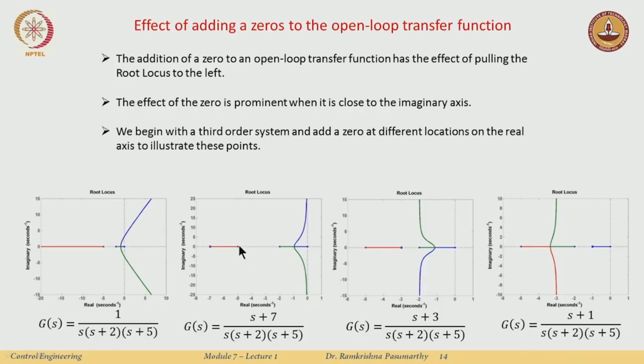So, this guy again will just move to the right and stop here, and now I see that the root locus has improved much, because if I were to deal with this gain here, you see that I am close to the verge of instability, right, this and this. So, this kind of adding a 0 makes my system stable because it is pulling this blue and the red lines to the left, but it may not be too good in terms of relative stability.